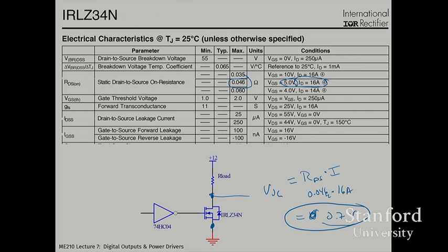And this is how we would operate the device. There'd be some logic circuitry controlling it. It has its own power supply. And this load is basically our motor. So when this thing is in the on state, current flows through this device to ground. When it's in the off state, that current stops. And this VOL is basically the voltage on the low side of the motor, and it's the voltage drop across the motor that determines the performance, the speed of the motor. So this is a pretty nice device from the standpoint of its ability to handle very high currents.